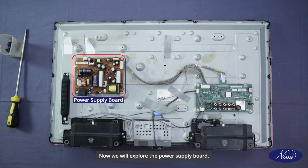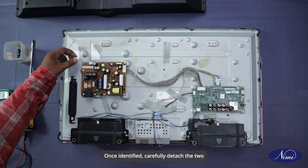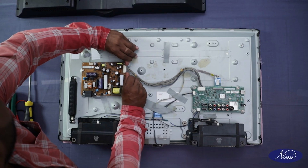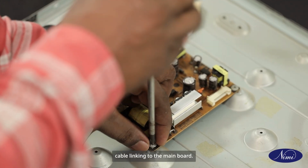Now we will explore the power supply board. First, identify the power supply board within the internal layout of the television. You can recognize it by the array of capacitors, inductors, and connectors typically located near the power input. Once identified, carefully detach the two main cables connected to the board. These are usually marked and may include the main power cable and the cable linking to the main board.